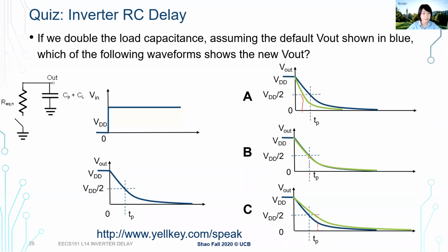Yeah, think about it. So we talk about this RC circuit, the delay, right? Different factors. So we're mostly talking about the internal factors of our gate, right? But what if I'm actually driving a much bigger load? I have a much bigger load capacitance. How is my circuit going faster or slower in this scenario?